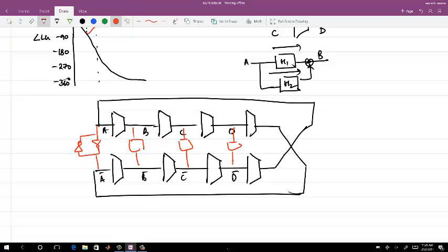Then it will not oscillate. It means the frequency at which you will oscillate. If the phase relationship gives you 360 degrees or 0 at some frequency, then it is going to oscillate, in the case of 4. But when you are trying to start the oscillations, let me say at t equals 0, you will have a steady state in this case where VDD is 0 and it will not start at all. So in order to start the oscillator, you need to start in an opposite phase.